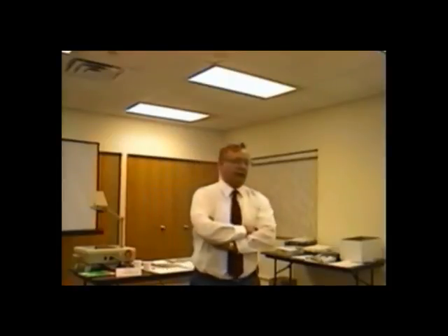They install 3/8. And then I say, well, what do you install with a 1.5 tons? Well, 3/8, right? And what do you install with 4-ton? Well, 3/8. What do you install with 5-ton? 3/8. So we install 3/8 for everything. So some got to be wrong. And we say, why? That's what we carry.